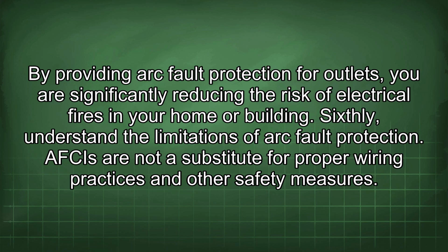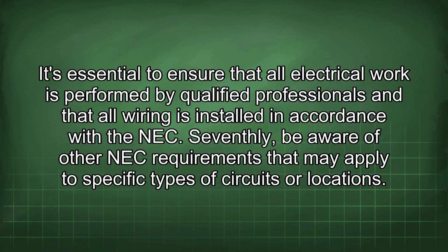Sixthly, understand the limitations of arc fault protection. AFCIs are not a substitute for proper wiring practices and other safety measures. It's essential to ensure that all electrical work is performed by qualified professionals and that all wiring is installed in accordance with the NEC.